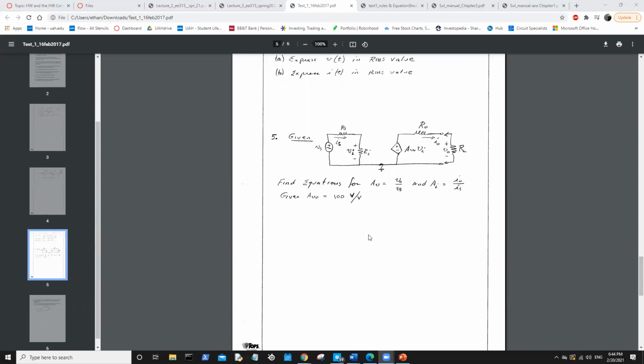We're going to need voltages divided by resistances here. So for our IN or IS, I guess, it's going to be VS divided by the composite resistance, summed. So VS divided by RS plus RI is equal to IN, and then IN goes over here.